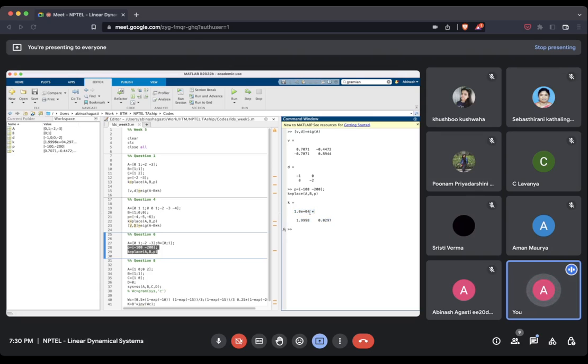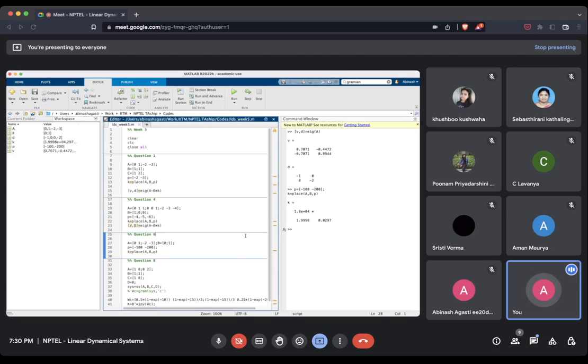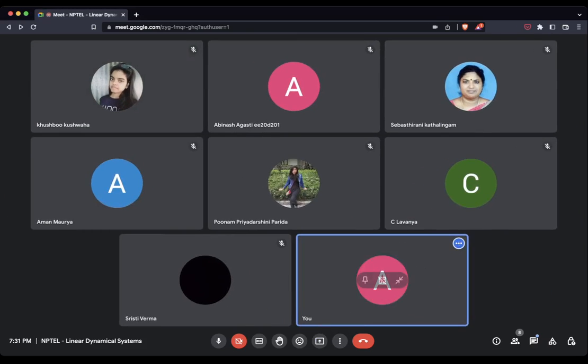So why is this happening? Think about it naturally. Your system was naturally responding to whatever input you had with -2 and -1 eigenvalues. So it had some e to the minus t and e to the minus 2t terms in its transient response. But now you want them to die so fast that you want e to the minus 100t and e to the minus 200t. Obviously, to achieve that kind of alteration on your system, you would need to place a significant amount of control input to obtain such better performance from what you originally had. That is why, while placing eigenvalues, we need to be careful not to place them too far away. Alright, is it clear?